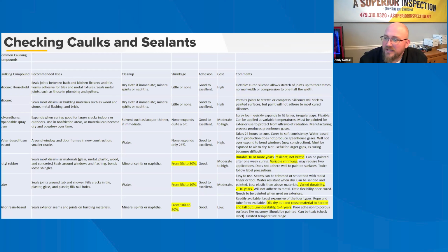A high-quality caulk installation requires appropriate ambient temperature, dry and clean surfaces, and an adequate joint gap to allow the caulk to act elastically without pulling loose from the two caulked parts. In addition, foam backer rod or bond breaker tape may be installed to create an appropriate caulk joint profile for adhesion, flexibility, and durability. Inspection of caulking is strongly recommended.